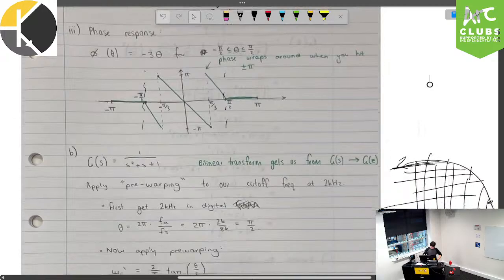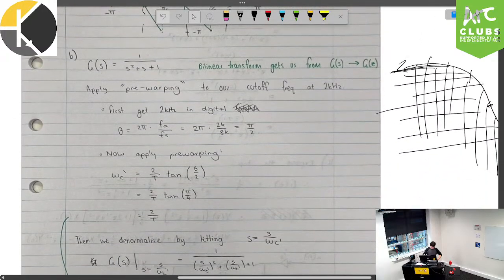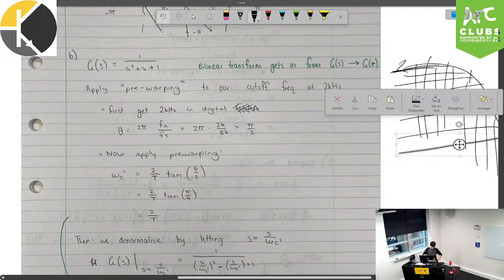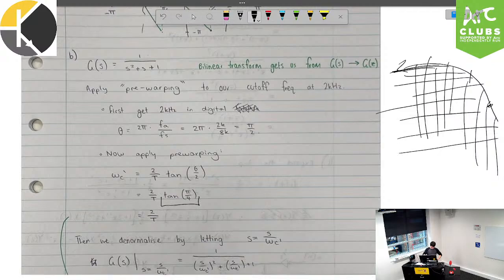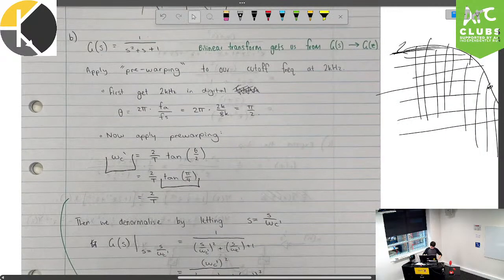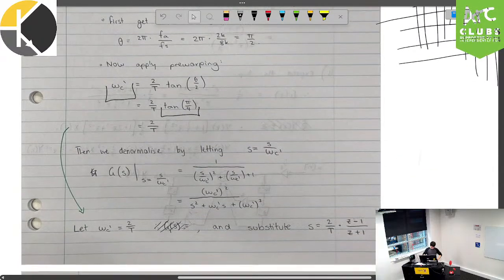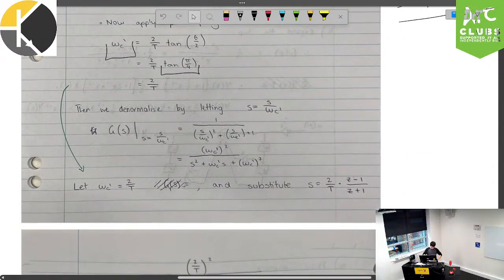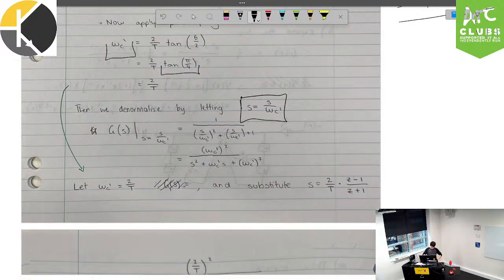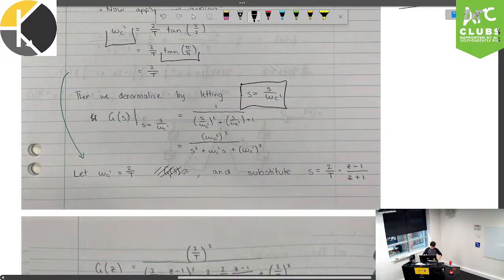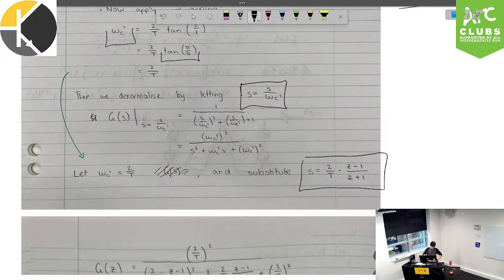So we're going to apply pre-warping by understanding that within certain ranges, the tan needs to be considered. Right over here, we're just considering the range at which we are dealing with our cutoff frequency. Okay, so denormalizing, we convert S into S on omega c, since this is pretty much scaling to pre-warp, and then we're going to perform the low-pass filter transformation.